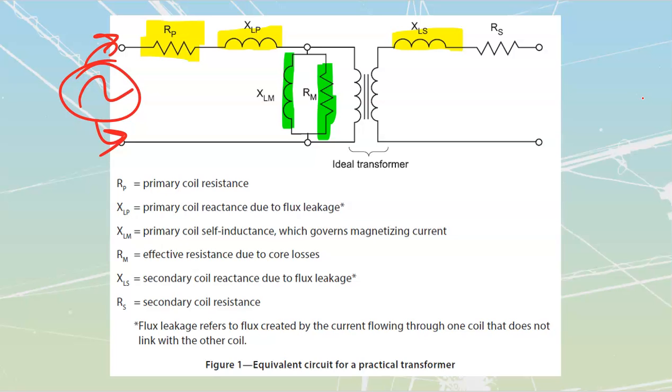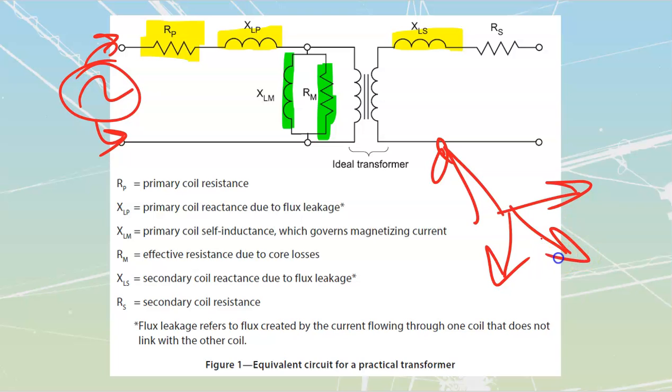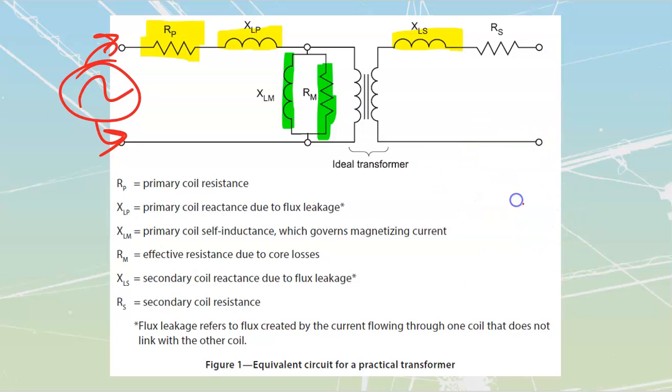Now, we're not going to go into a crazy amount of vectors and draw these things all going in every which direction. We could do that, but it's really not going to do a lot for us. Just know that we've got a bunch of inductive and we have got a bunch of resistive. There can be a small amount of capacitive, but it will never be enough to counteract the overall effect. And if the overall effect is going to be RL, resistance and inductance together, well, then what do we know? That we're going to have a lagging type of power factor for this.